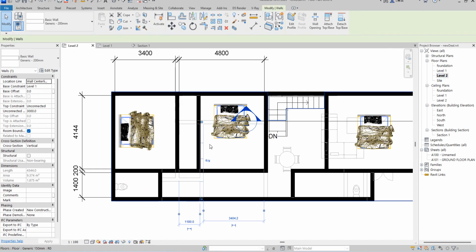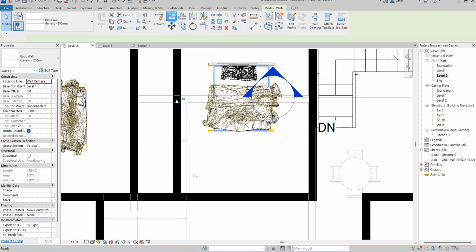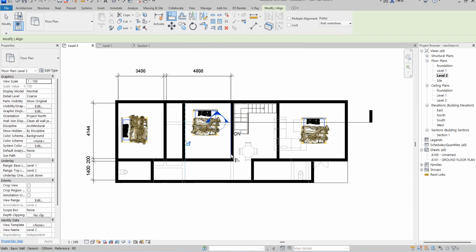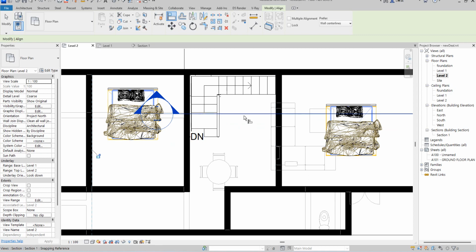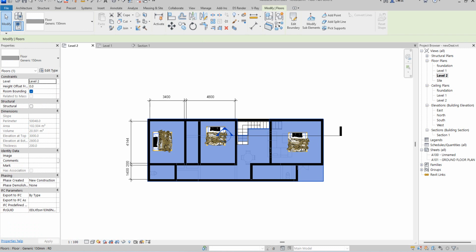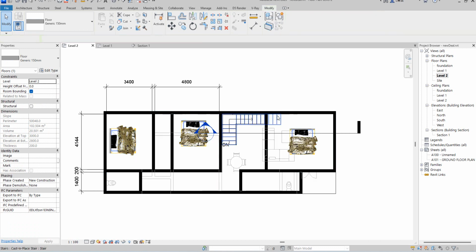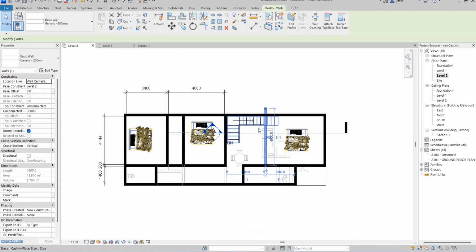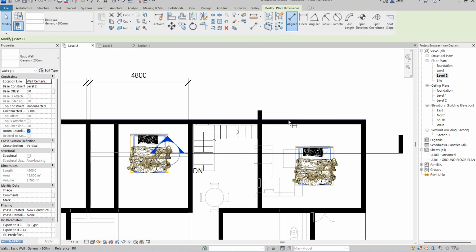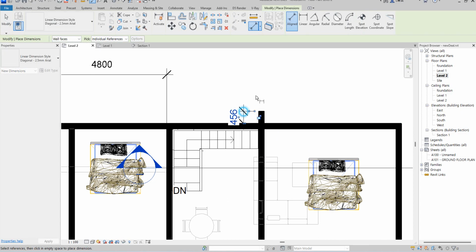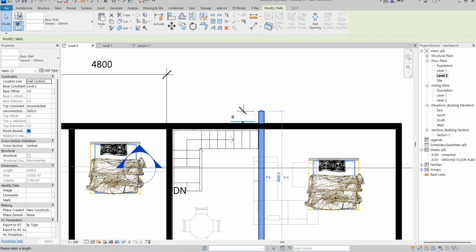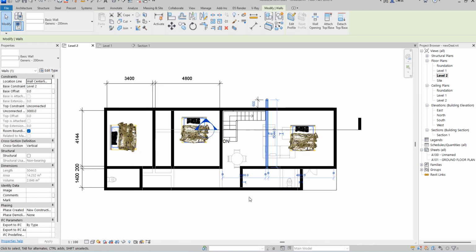So now let's go to the upper floor where we are doing the design. You can tag this one to this, so the room is there. Now what I need is to complete this at this level, then move on. Because of the design and other things, I'm going to expand this. I'm going to take it up, just get it done for 5. Now I'm going to say 600. So let's say 600, that's 2 feet precisely.